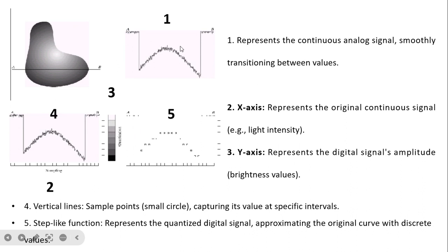For example, here we capture the signal. Now we require to convert it into color. So if we want to convert into a 3-bit image, that is nothing but 8 colors, so we are using these 8 quantization levels, and based on their intensity they are converted to a particular value. Now here instead of taking all that continuous value, we are taking the sample at a particular interval, and they should satisfy the Nyquist equation. Then this small circle is nothing but the samples we are taking.